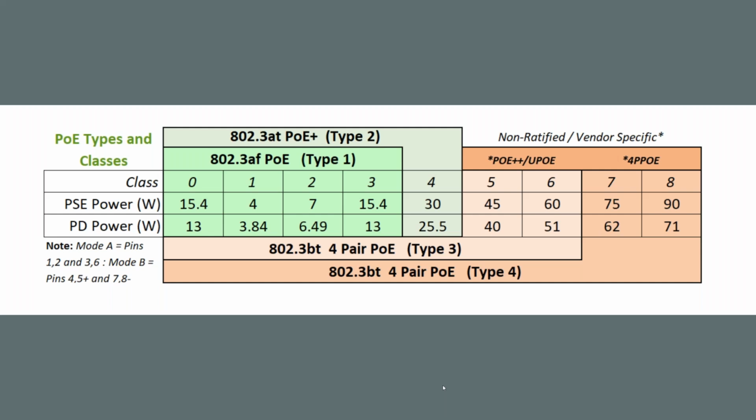The reason they did that is that when buildings were pre-wired with Ethernet jacks, people were plugging in devices, and if it wasn't the right voltage, it could cause problems for those devices. So what this does is say, hey, we want to know that this is really 48 volts. Are you compliant? Yes, you are. We'll take the power. So they created the standard.